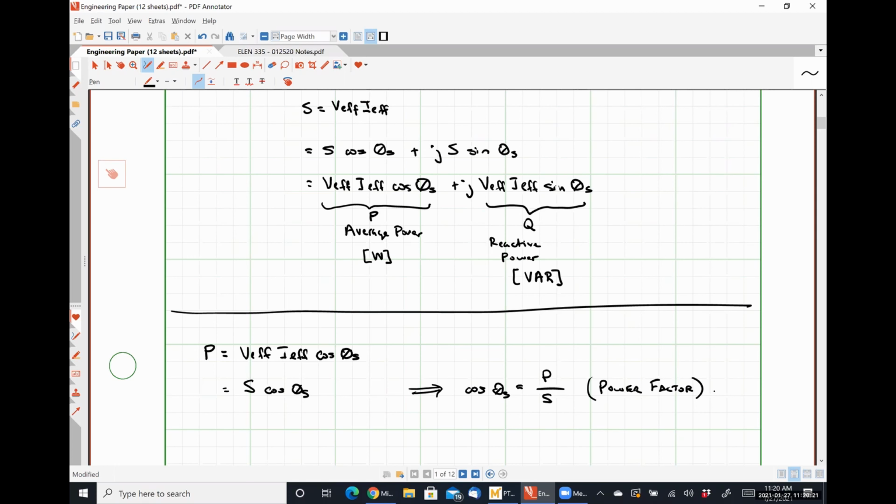This is the reason for the concept of power factor correction that we're going to talk about later. If our power factor is too low, it means we're running our system inefficiently, and it's costing the power company money because they have to generate it whether or not you're actually going to use it. If they didn't generate enough apparent power, brownouts and things like that would occur.